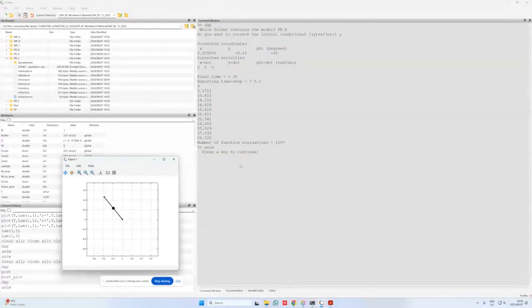All right, and you can already see from the fact that I'm using a final time of 30 seconds, the motion of the pendulum rod is already significantly slower to increase than what it was when I had a constant torque on the system. So something tells me that there is an effect of the driver constraint even in the presence of this constant torque.